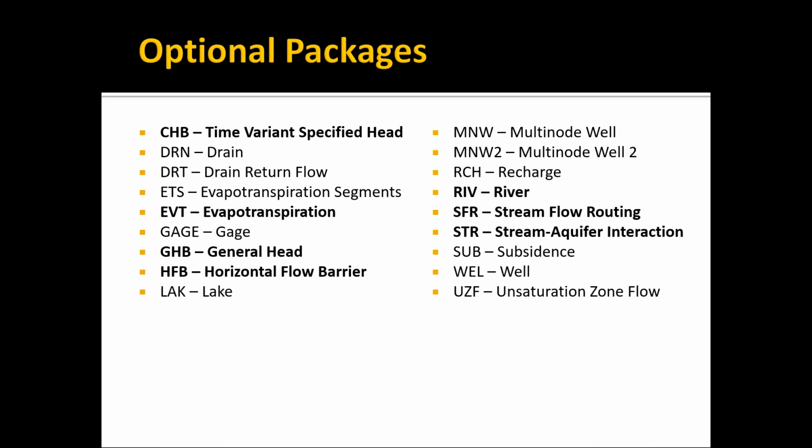What if you have a well screen that spans multiple layers in your model? Or what if, when the water table drops, the well can't pump the full rate? Well, several years after the well package was released, it was part of the original MODFLOW model in '83, they developed the MNW and then the MNW2 package, which provide a much more sophisticated representation of wells.